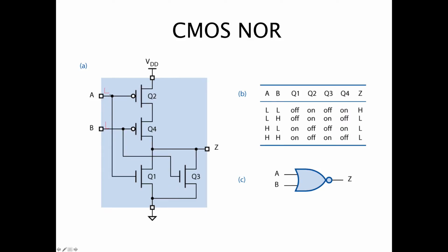Since there's a bubble, that turns on these transistors, so they act like switches, and that's a short. All the current can flow there. Another low to that bubble is also a short. And so we immediately have a connection from Z up to VDD. With just a few things, I can figure out that's a high.